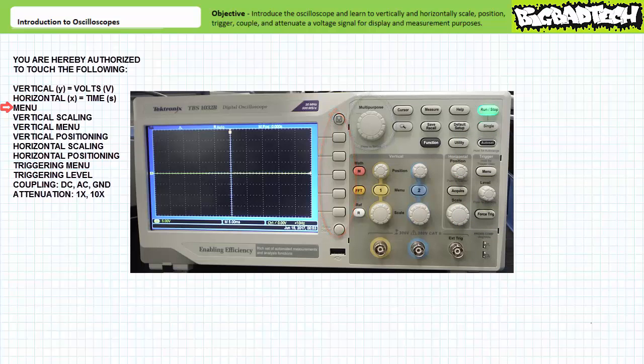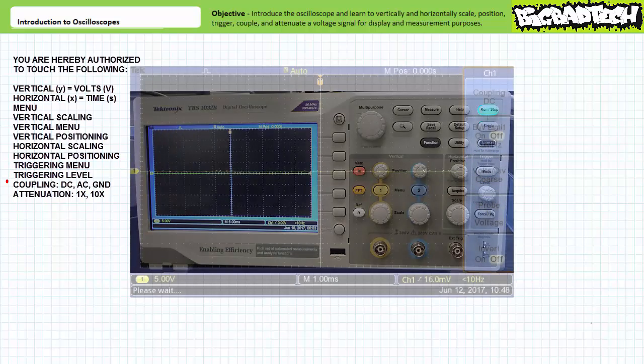The vertical group includes 2 channels. Each channel has a means of scaling the volts per division, a means of accessing that channel's menu, and a means of vertically repositioning that channel on the display. The horizontal group includes a means of scaling the x-axis seconds per division and a means of horizontally repositioning that channel on the display. The triggering group includes a trigger menu and a means of adjusting the triggering event up or down. Triggering must occur off an event that actually occurs on a regular basis.